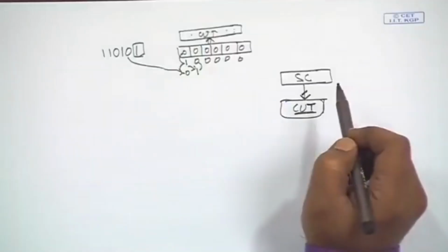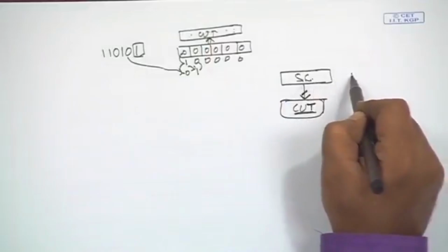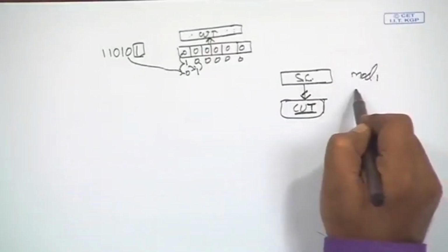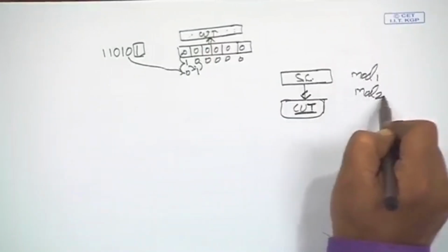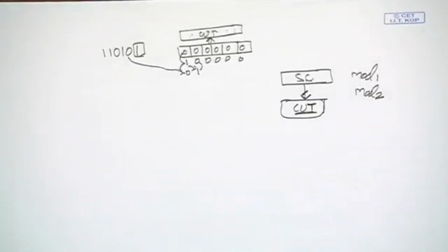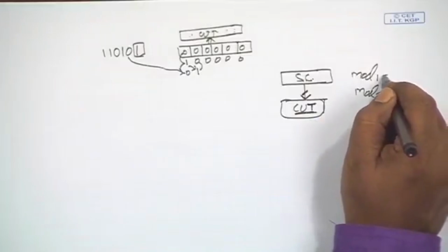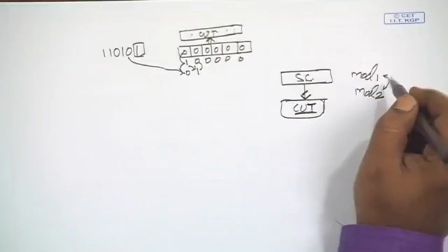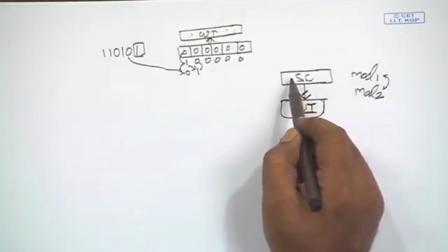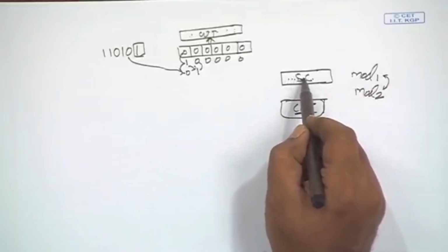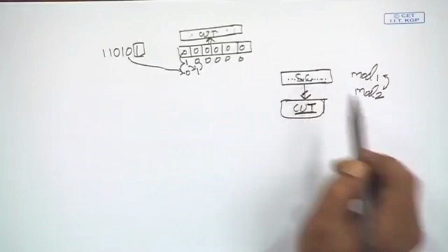And in fact, what we are looking for is that we will do some modification to this scan chain. Suppose I have two modification schemes, modification 1 and modification 2. I do not need the exact power values for modification 1 and modification 2; rather I need a measure by which we can compare which one will be better. It has been seen that if you compute the transitions occurring in the scan chain itself, that is a good estimate.